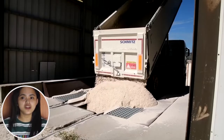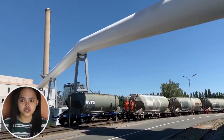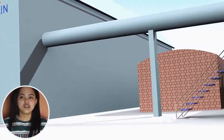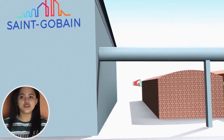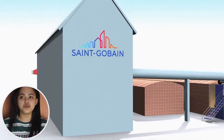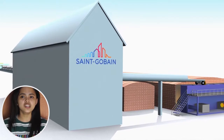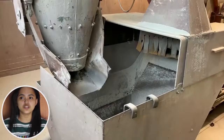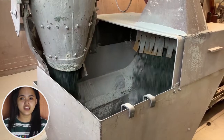The various raw materials are transported to the factory by truck or train and are stored in silos in the batch house. All these raw materials are rigorously checked to guarantee the purity of the batch. Each material is weighed by scale before being delivered automatically into the mixer. This is when recycled glass is added to the batch.